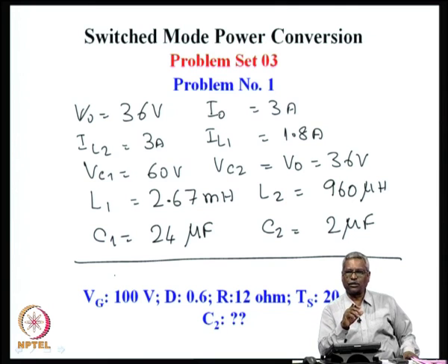Then the inductor voltages can be studied for the dynamic property of L di/dt, which is the voltage across the inductor. From that, it is possible to find out the current ripple, and if the current ripple is known, then we can find out the inductor to be used. In the same way, from the capacitors, if we know the voltage ripple that is allowed, it is possible to evaluate the required capacitance.